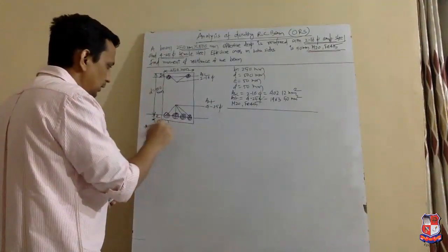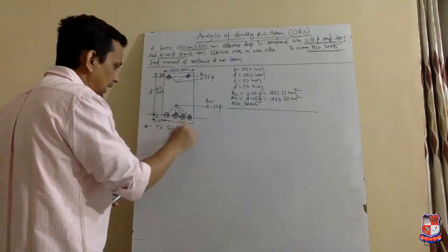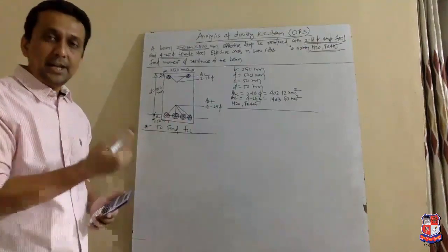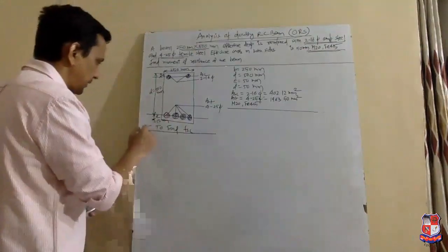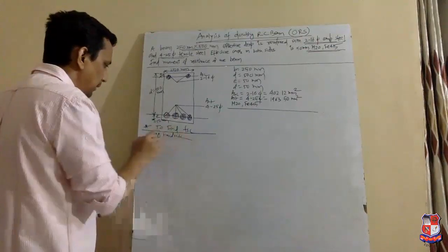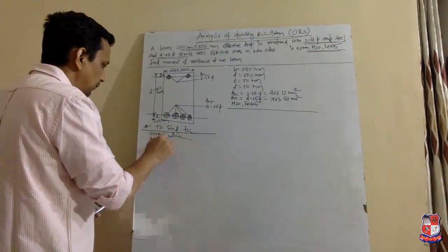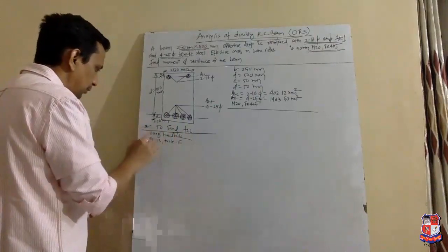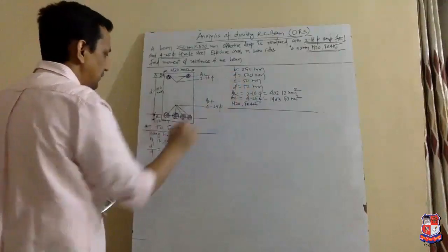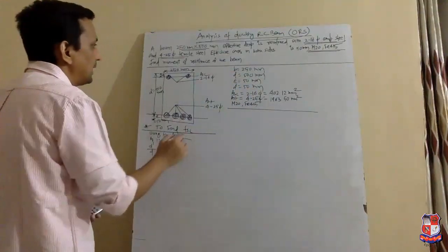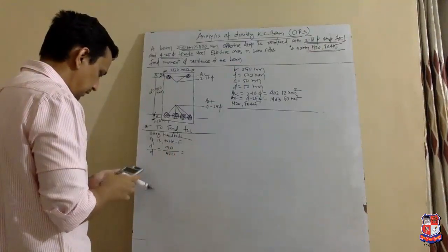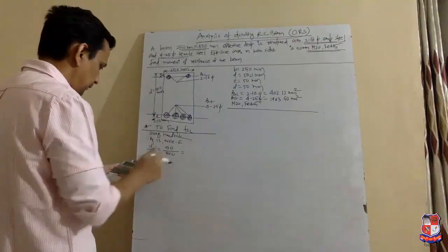So first, we find FSC. Here again, we will find it using the handbook as well as IS 456. First, using the handbook, page number 13, table F. For that, we need to find d dash upon d. We have d dash 50 mm and the effective depth is given 500 mm. So 50 divided by 500, we get 0.10.